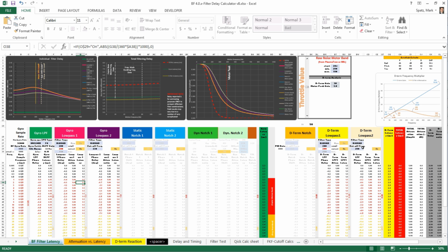How high can I move that? I don't know. What's your base noise? What kind of props are you using? If you're using really junky props, you're probably not going to be able to run it very high. So spend an extra couple bucks and get some really decent props. And if you don't know what props you should buy, I did a video, which I'll link to upper right, for the ones that had the best performance, because you want clear props as well. See, it gets all kind of complicated.